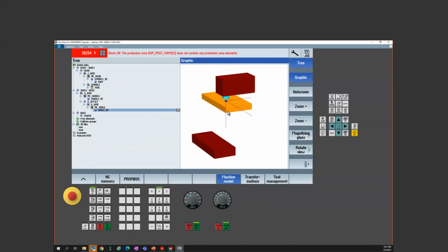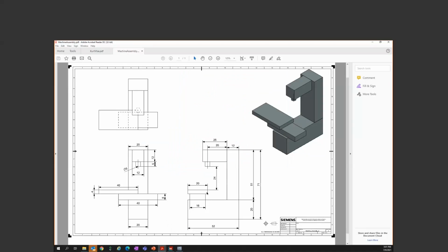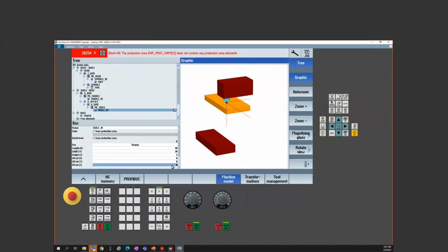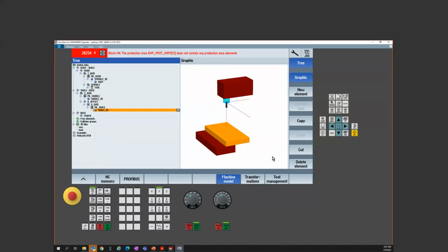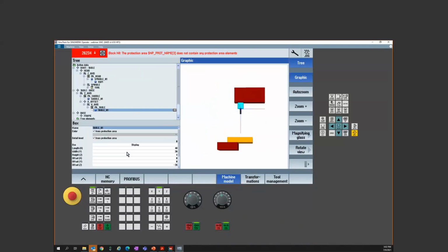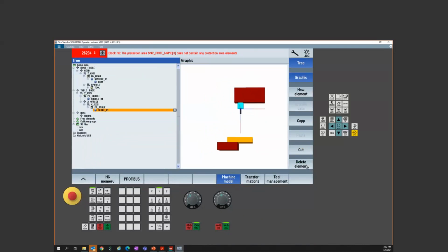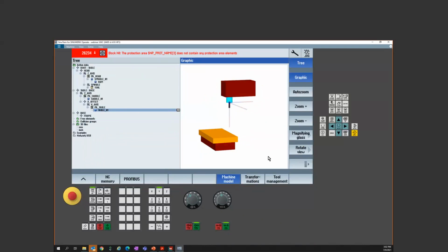So we got to shift it down in the Z. Quick look at my print. So we got 24 plus half its thickness, so 26 will get me there. So I can do minus 26. That'll position me down. So I'm right on the surface. So now I just have to shift it, and I shift it in this case by half its width because the edge of my spindle, and I'm at 0, is going to be the edge of my table. So just shove it back in the Y a negative 10, half of its width, and voila. Now I have a table centered.